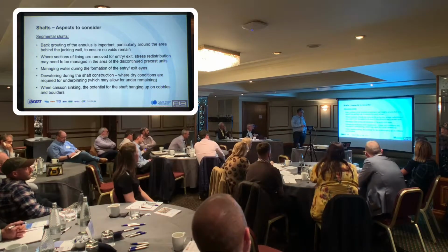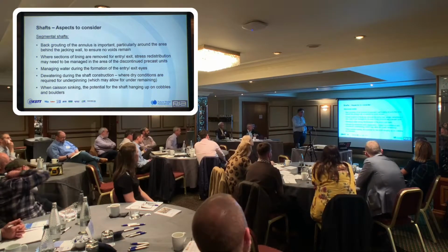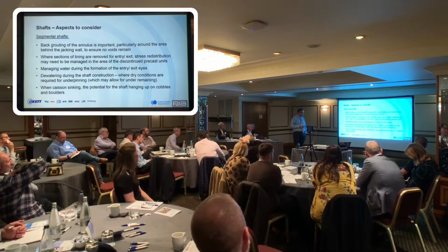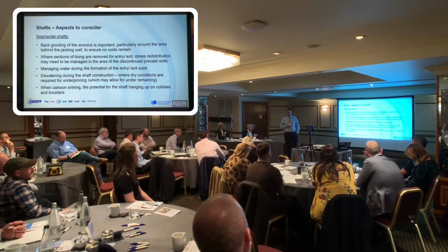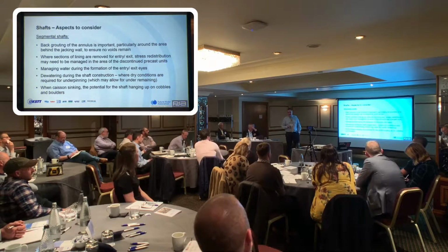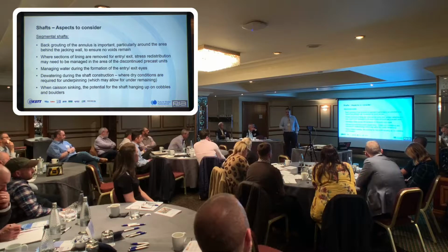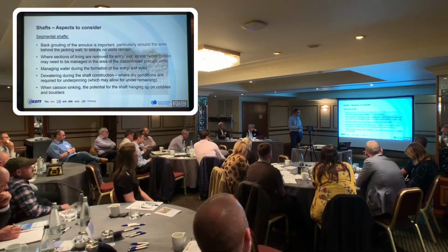When caisson sinking, it's important to understand the potential for the shaft hanging up or getting stuck on cobbles and boulders. So again, as I just mentioned, with a wet caisson particularly, if you're intending to dig through water, you haven't necessarily got access to clean out where you're going, and that can be a big problem.